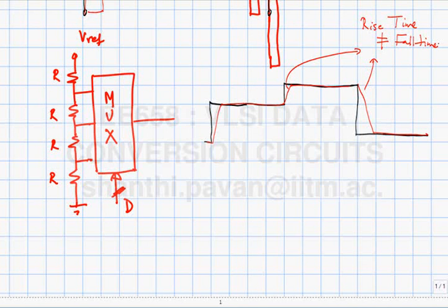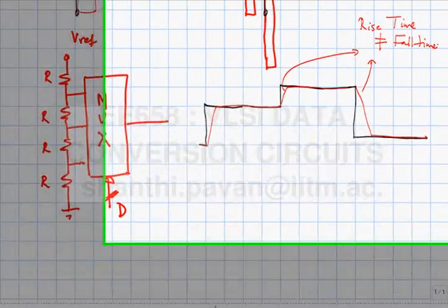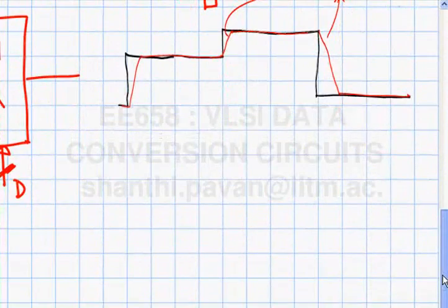So the same thing will hold also. Even though you may not be able to see it at this point in time, it's conceivable that if you make a better DAC with a larger number of levels too, that might hold in general. So by design you can probably make the two of them the same, but in practice there will always be some finite difference. Let's see what happens when I put a sequence.